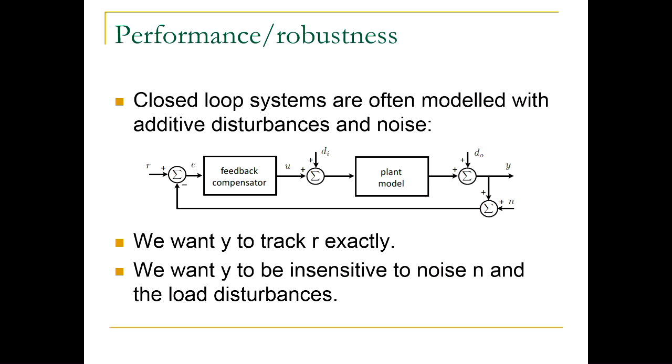So no, seriously, in many situations you are dealing with exactly this situation where r is low frequency and n is high frequency. So you want to reject n, but you want to follow r. And you can do that, and we will learn how to design control systems that are insensitive to noise, but follow references. And the frequency domain analysis will help us achieve this.